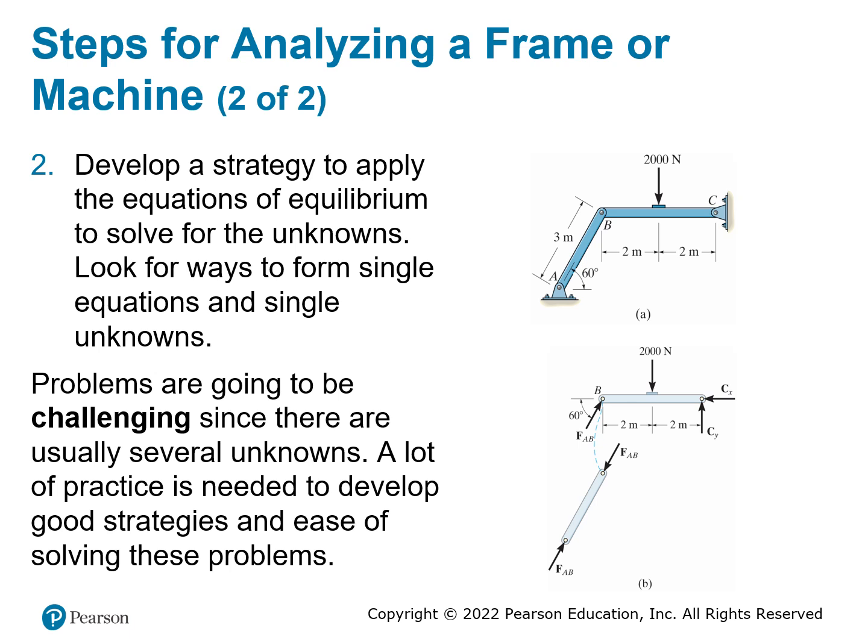When you choose point C, you decompose FAB into the X and Y components. The X component is not going to give you any moment because it's along the line, which is zero perpendicular distance away from this point. You only have the Y component that will generate a moment. So it will be a lot easier to solve this problem.